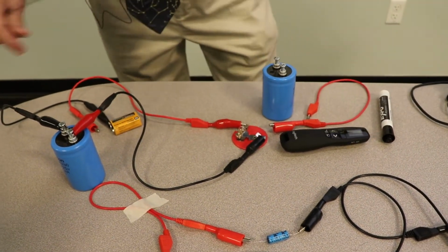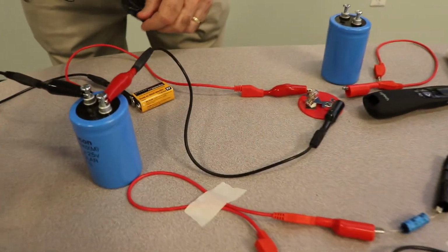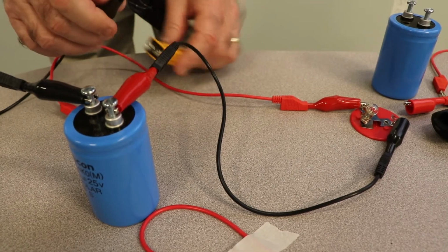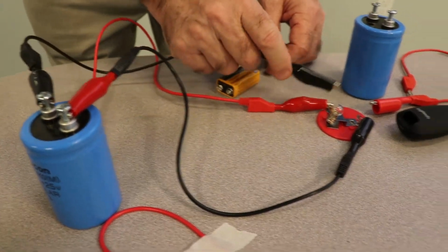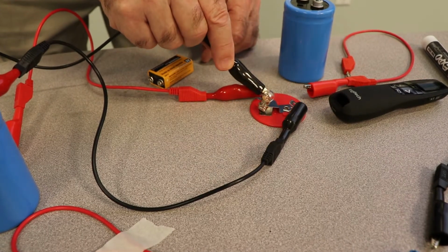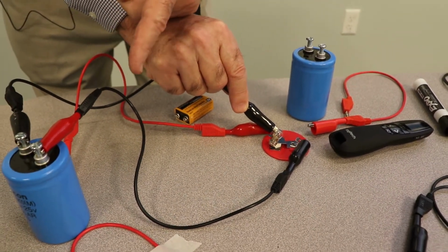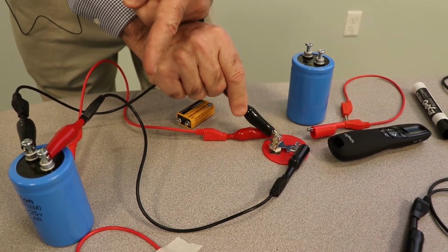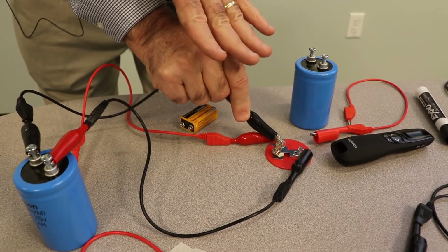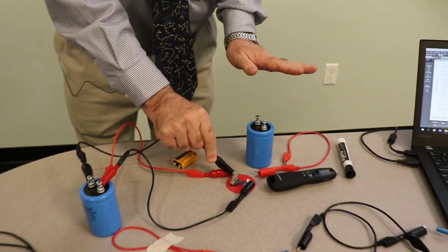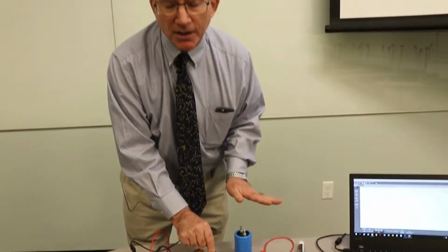So now the capacitor is fully loaded with charge. So what I can do is I can take this lead right here that came from the battery, and now just put it right here and discharge it. So you see that? A capacitor is kind of like a battery. But you can see it was really bright at first and then dimmed down. A battery's bright all the time until the battery runs out of chemical material, and then it goes down rapidly. But for the longest time, a battery's nice constant voltage.